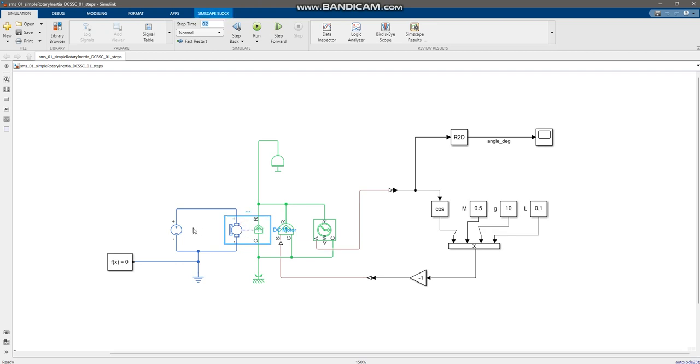But since we have now dealt with the motor side using a combination of relatively simple blocks with the hard tasks hidden within a black box, we can just remove these blocks, bring in the Simscape blocks for the stepper motor, connect the controllers as we would in a physical world, and provide the PWM signal as we would in a physical world, and run the simulation and see what the performance is. So that's the advantage of sticking with Simscape blocks, and we'll see that in our next video.